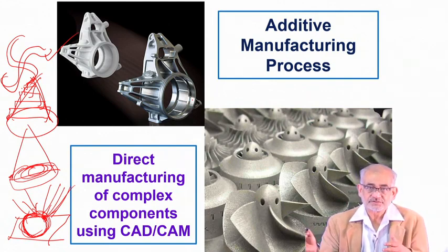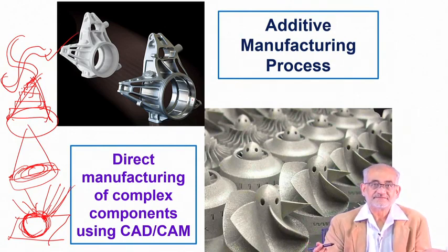Instead of doing all those laborious, time-consuming, and energy-intensive processes, I can simply use a powder feed and a source of heating through laser, and I can build the final component in one shot, one single manufacturing stage. So that's the advantage and beauty of additive manufacturing.